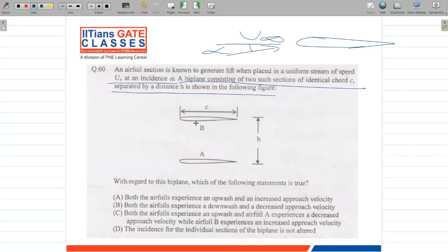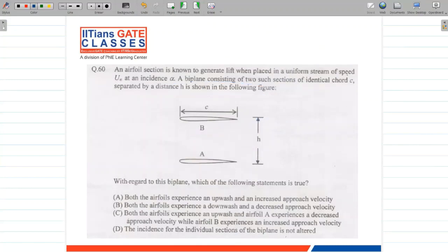So there's a biplane configuration where you have airfoil B and airfoil A. They are kept at a vertical distance of h from each other, and both are identical. Both are exactly the same airfoils with the same size, same family. With regard to this biplane, which of the following statements is true? Both airfoils experience an upwash and increase in approach velocity. Both airfoils experience a downwash and decrease in approach velocity. Both airfoils experience an upwash and...